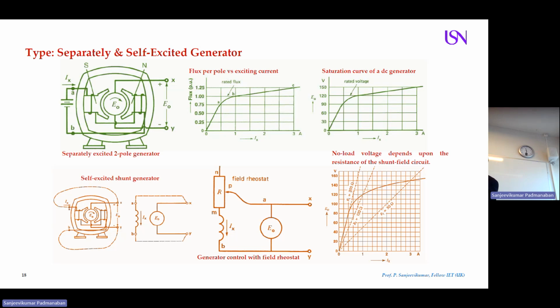What I have to do practically in the laboratory setups, as you are going to see in your lab, is connect a rheostat, which is a set of resistance, in series between the DC source and the field winding, which is the stationary part of your machine. See, I am repeating the words: stationary part, field winding. These are the same terms. Then we are going to have another DC source, which is connected to your rotating part, called the armature winding, again through another armature resistance.